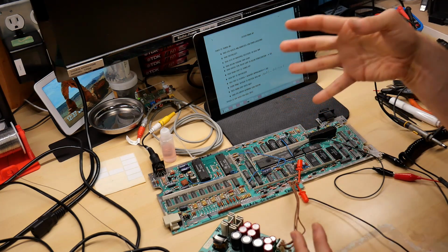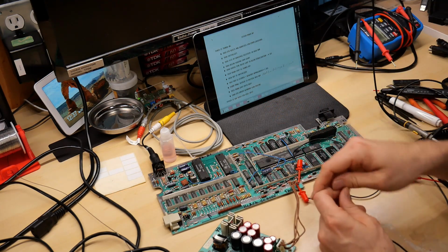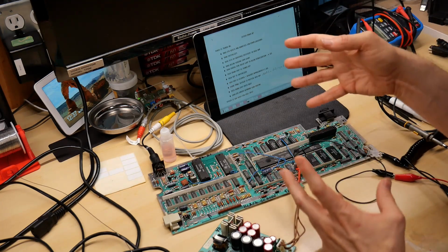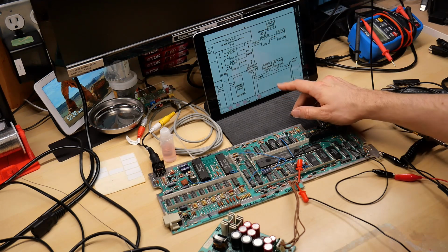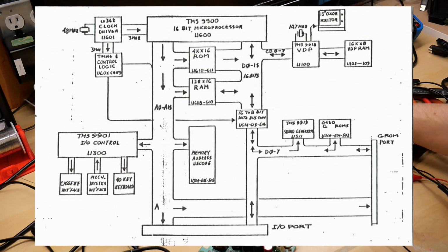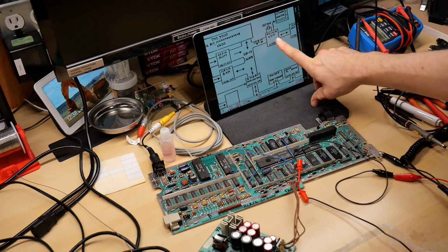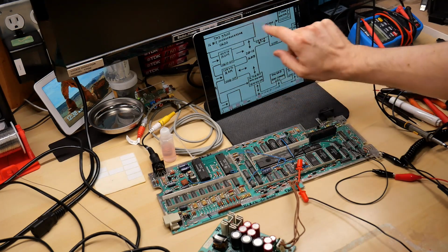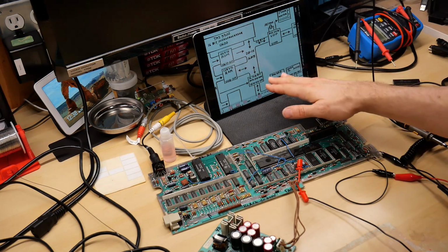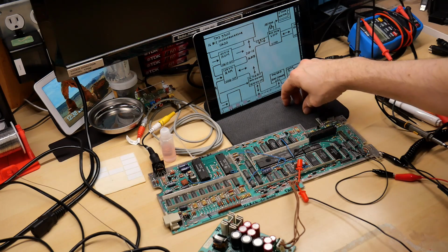Now, unfortunately, when you have faults on the data bus, they're not easy to figure out because it's exactly what it says. It's a bus, and there are a bunch of things connected to it. If we look at this block diagram, there's 2 additional components on the bus. There's the video display processor, and that's on bits 0 through 7. And then there's also the 16 to 8-bit converter device. So realistically, the video processor could be faulty, this converter could be faulty, the RAM or the ROM or the processor. Any of those can be having an issue, and that could cause those issues on the bus.